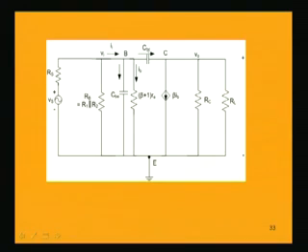So, in order to separate out the input and output circuits, we have to distribute this capacitance CBC in the input and output circuits, thereby removing it from this part. That can be done by taking help of a well known established theorem known as Miller's theorem. So, what is Miller's theorem and how we are going to apply it in this circuit to simplify it, that we will be discussing first.